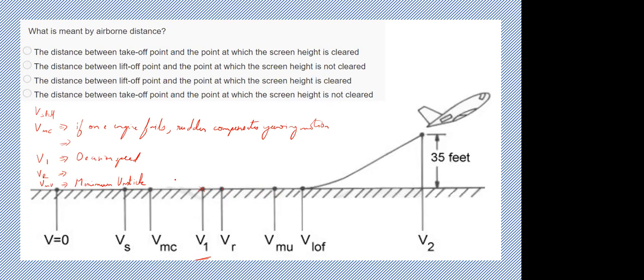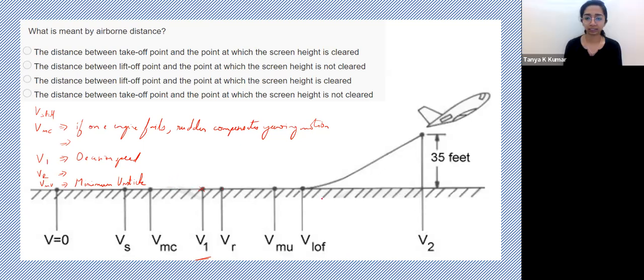It is the speed at which the undercarriage, the back wheels haven't unstuck yet. But after just passing this speed, the undercarriage will also come up. Yes. So if you were to take off at this speed, the undercarriage would just touch the runway. So you need to take off at a slightly higher speed, which is the V liftoff.